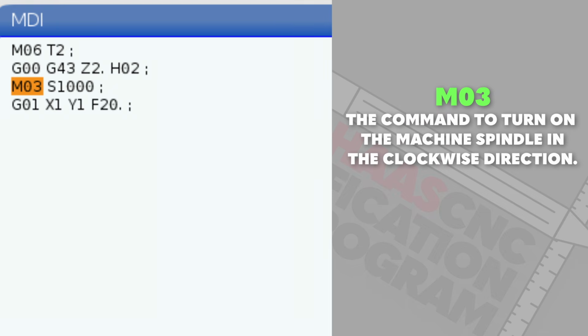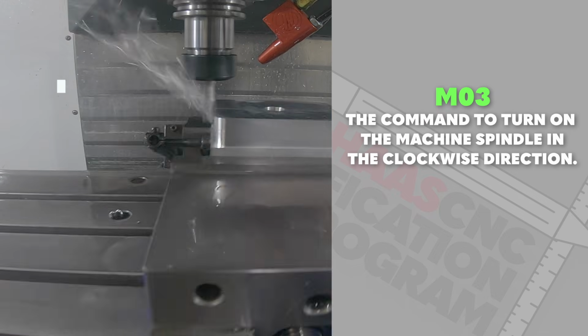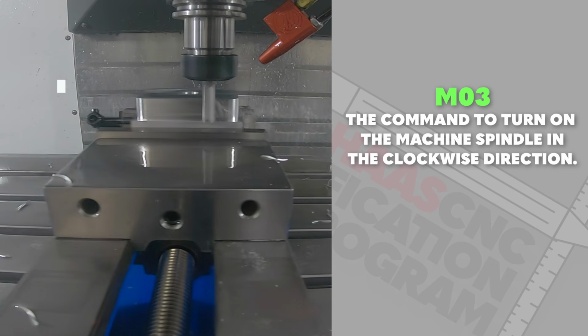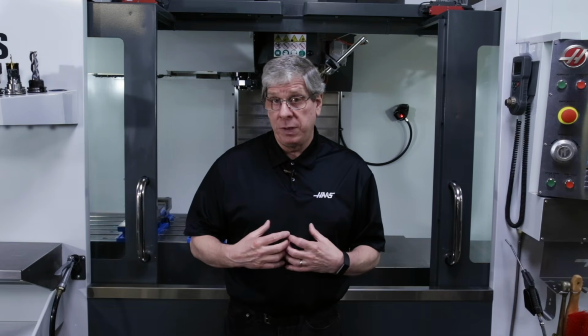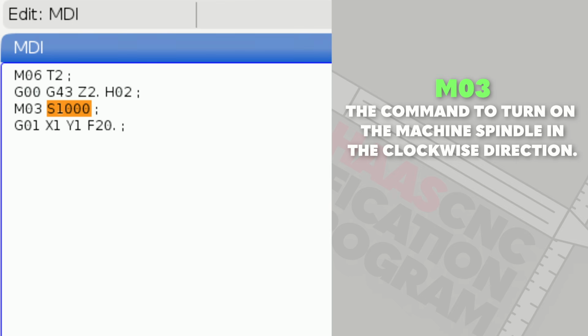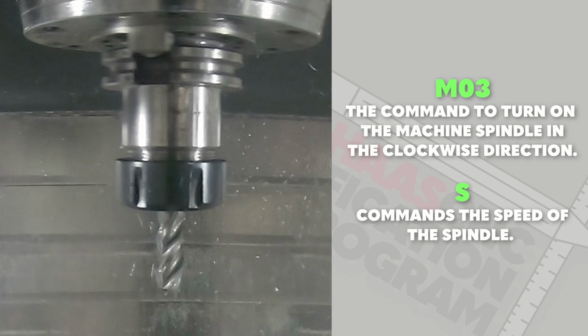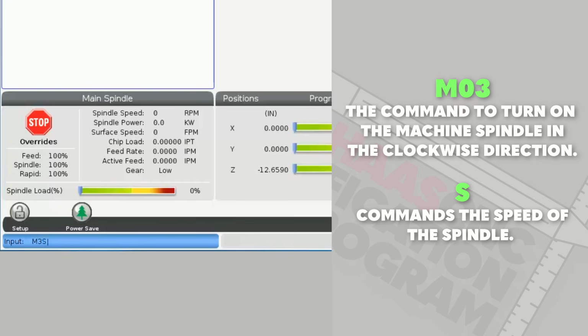For example, the code M03 is the command to turn the machine spindle in the clockwise direction. But it doesn't tell the machine what speed to rotate the spindle. The letter address S is the speed command, so we would program M03 S1000 to rotate the spindle clockwise at 1000 revolutions per minute.